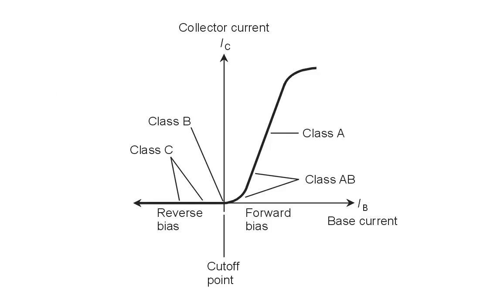In an audio amplifier, in which we were dealing with the previous question number 37, we were talking about linearity for the actual input waveform. That requires that we go only within that straight line part of the curve. But if we want to use a radio frequency amplifier, the modulation envelope is a different animal from the signal waveform itself.